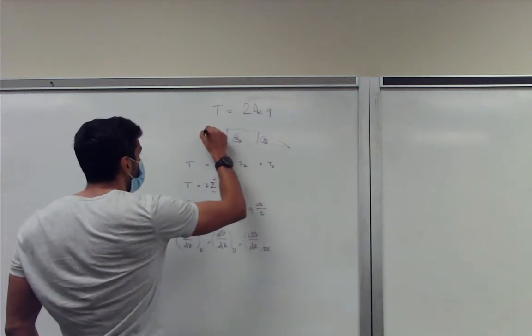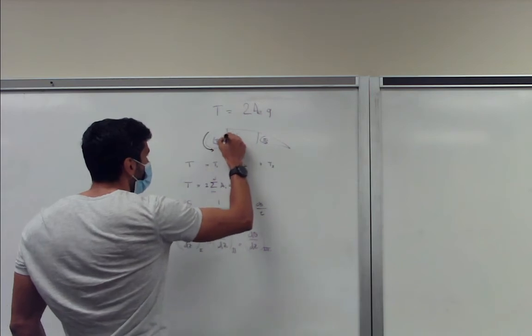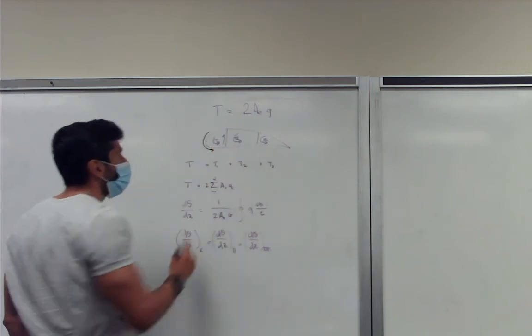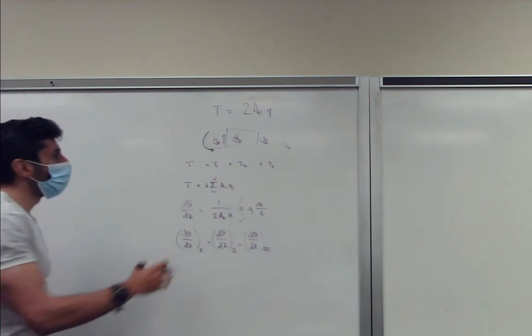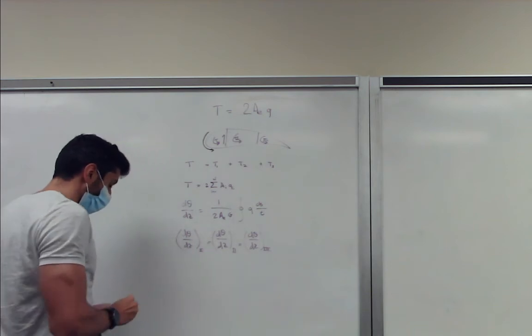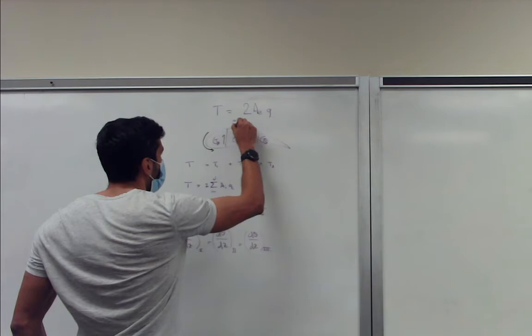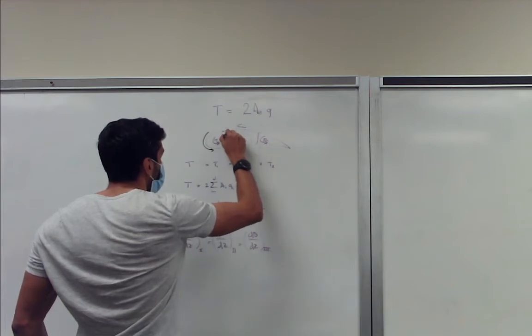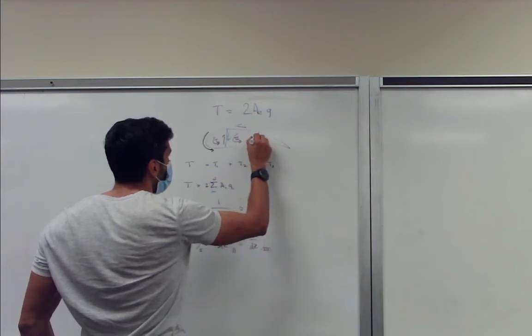In this case, we'll have q coming like this. This side of the wall will go up, because you still have to maintain that counterclockwise rotation. In cell 2, we draw that in blue, we'll have a shear flow going down, going to the right, going up.